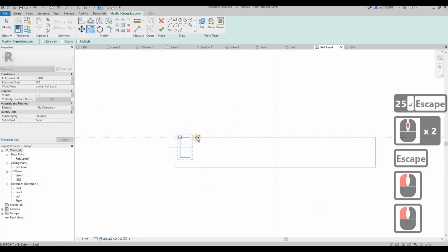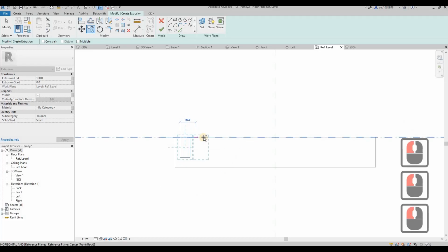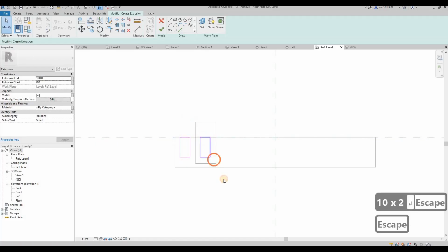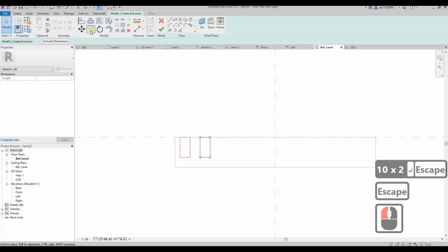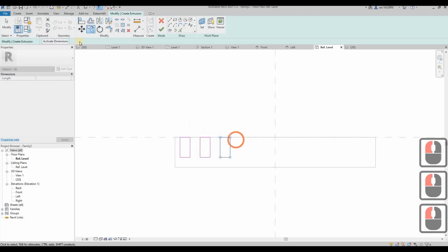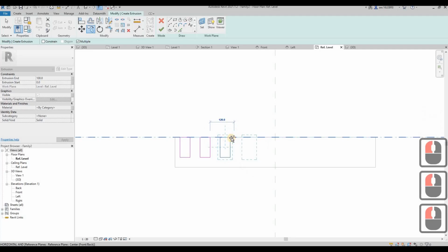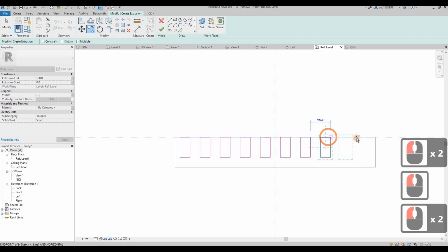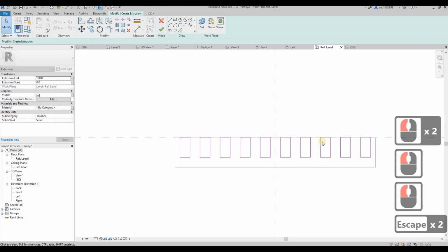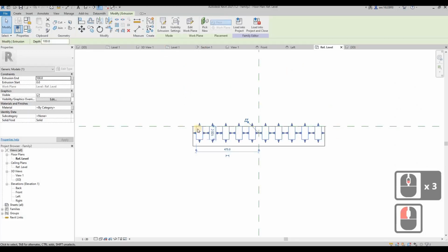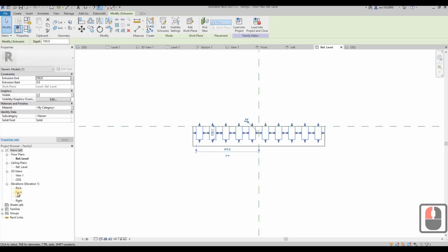We copy this one 100 mm because we know the spacing is 50 mm. Okay, by selecting this, then we click on copy, then we snap on here, then continue to copy, click here, multiple, snap to here, and put here. We can continuously copy the Louvres. Okay, so this is the extrusion of the Louvres. Click the green tick, then finish our extrusion.